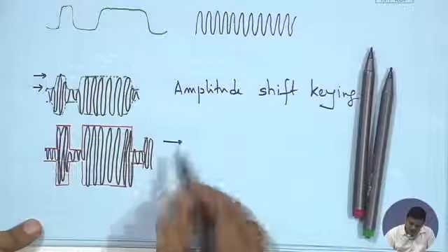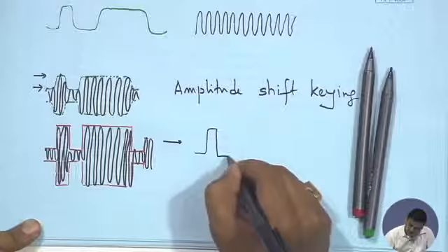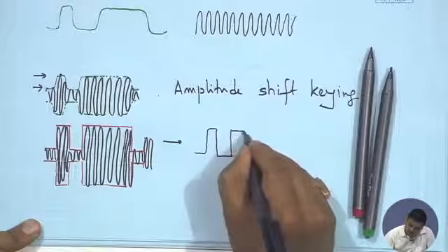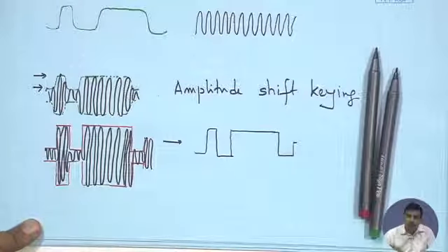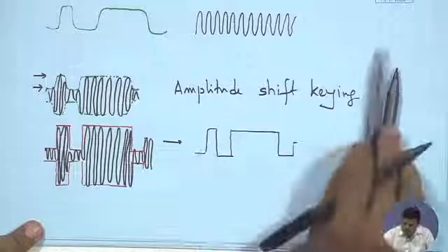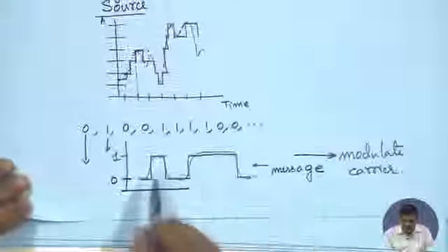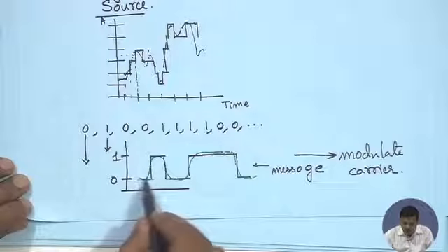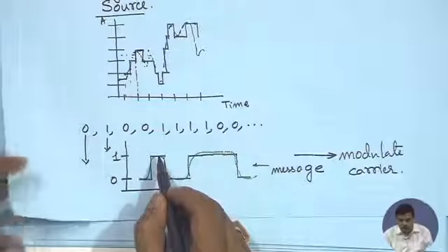So when your amplitude modulation receiver acts on this particular signal, it's going to generate the envelope of the carrier, or the amplitude. It's going to generate this waveform. Now, once you have generated this, you can reuse your earlier mapping, that if the signal level is here, I would consider a 0 has come. If the signal level was there, I would consider 1 has come.